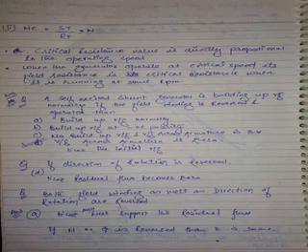A self-excited DC shunt generator driven by its prime mover at rated speed fails to build up voltage across its terminals at no load. What reason can be assigned for this? The field circuit resistance is higher than the critical resistance. The initial shunt field MMF does not assist the residual magnetism. Between A and B, you have to pick one.